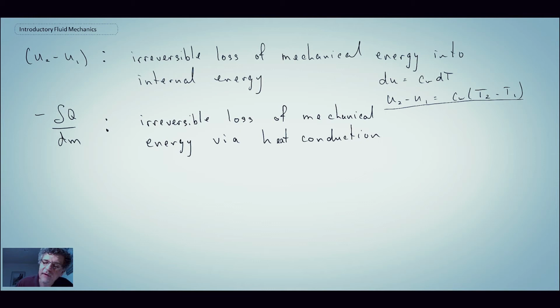So what happens here is the fluid heats up. You have convection, so you would have Q convection here, and then Q conduction going through the walls. That would be the heat loss. That's where the energy goes: into the surrounding environment, air, soil, whatever your pipe might be flowing or sitting in. That is the energy loss mechanism.